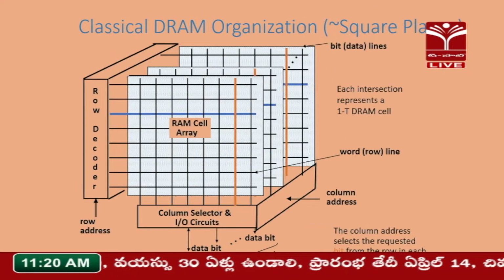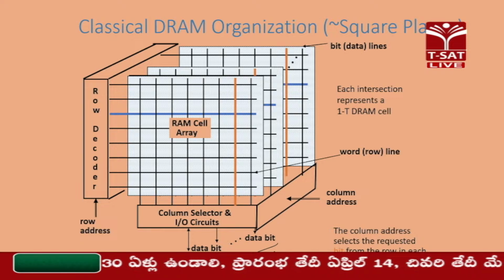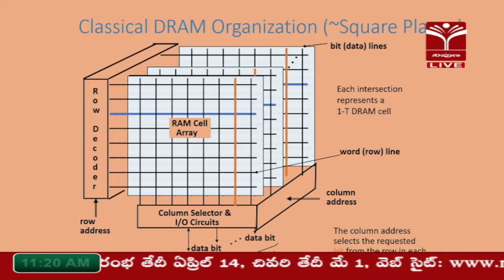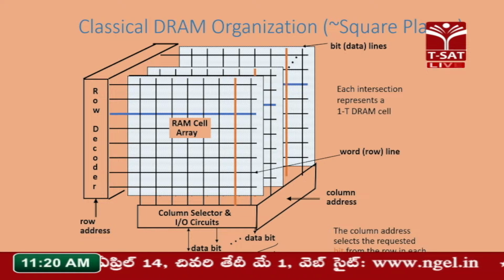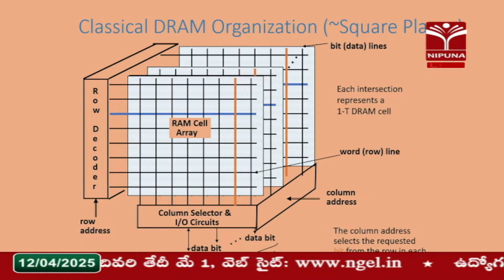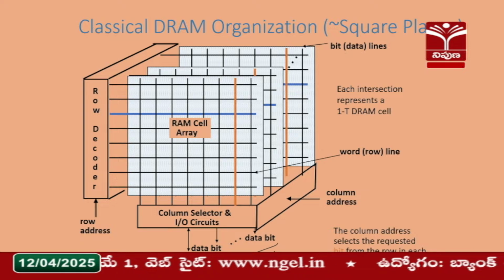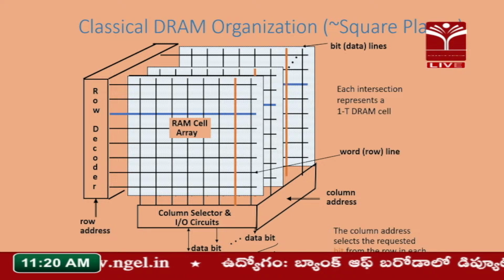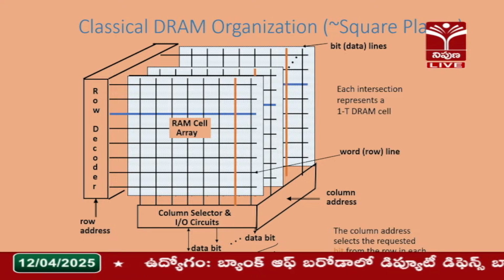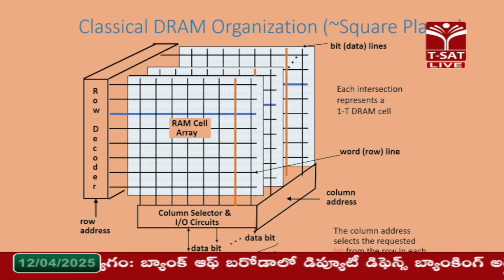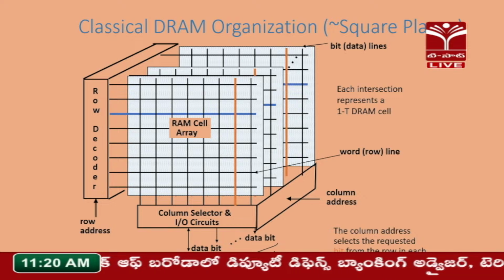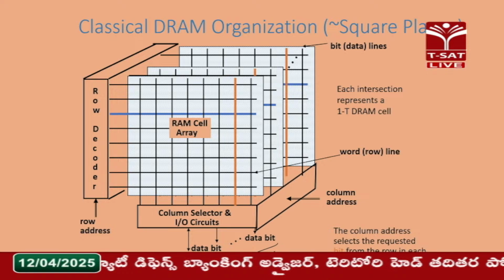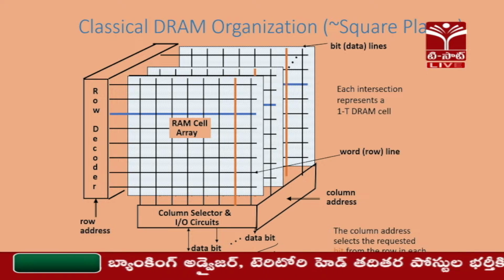Okay. And in a DRAM organization, the DRAM has multiple of these RAM cell arrays organized in both rows and columns. So it has more column address space that you can see, and you have more planes of this data arranged in what we call pages. So the DRAM has pages. Each one of the white boxes you see is a page. So there are multiple pages within the DRAM that are organized in a 2-dimensional way. Right.